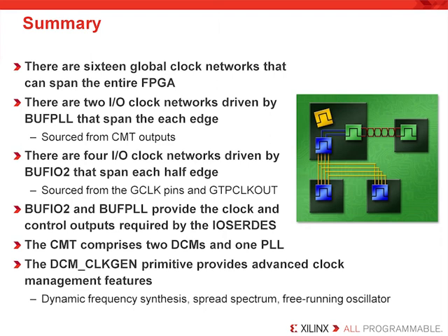The BUFIO2 and the BUFPLL provide the clock and control outputs required by the I/O SerDes resources. The clock management tile, or CMT, comprises 2 DCMs and 1 PLL. The DCM clock gen primitive provides advanced clock management features that we haven't seen before at Xilinx, including dynamic frequency synthesis, spread spectrum, and free-running oscillator behavior.